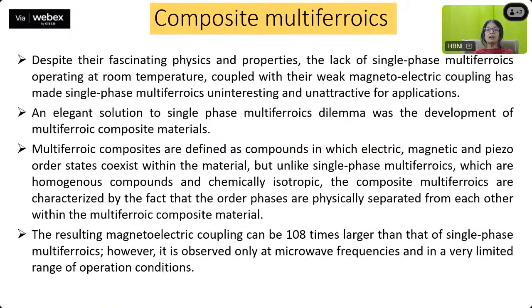So what are composite multiferroics? You don't have really too many single phase multiferroics at room temperature, and whatever you have, they have very weak magnetoelectric coupling. So single phase multiferroics are not really very interesting for applications. What you can do is develop multiferroic composite materials.